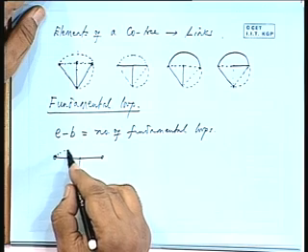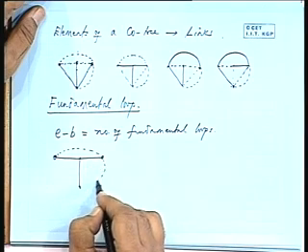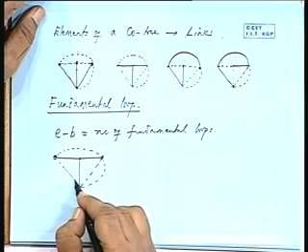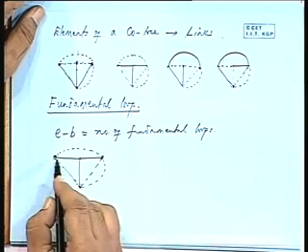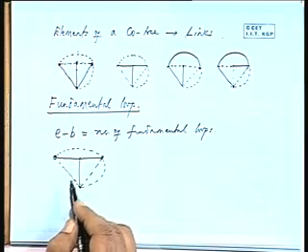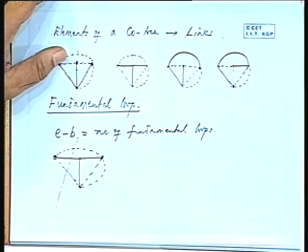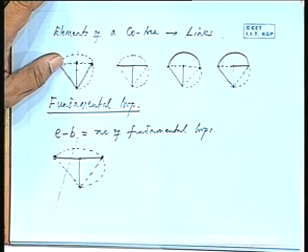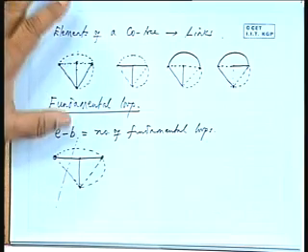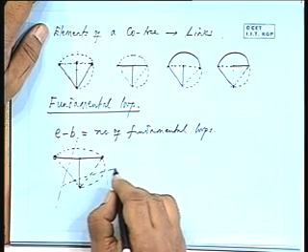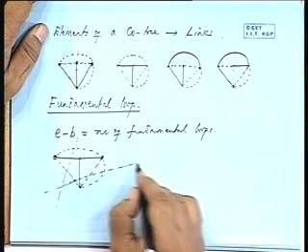okay, and these are the elements of the core tree, that is the links. Now you cut one branch of the tree at a time and separate the graph into 2 subgraphs. So I can cut along this, this is a cut set, okay, fundamental cut set. Then I can cut along this is another fundamental cut set.